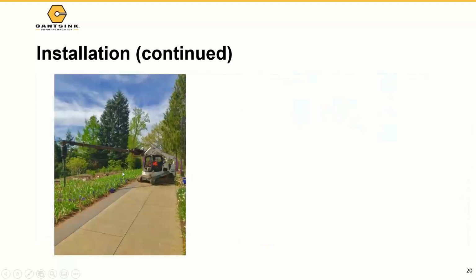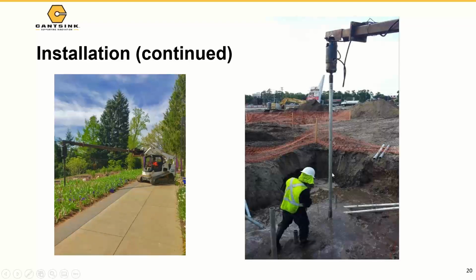This is, I believe, near Atlanta, installing this helical. That's a 2 7/8-inch outside diameter shaft. This one here, I don't know, there has to be, because there is no torque indicator over there. They must be using pressure gauges that are calibrated, because there is no torque indicator there. And you can see the water over here. I said they can really install them almost in any condition.